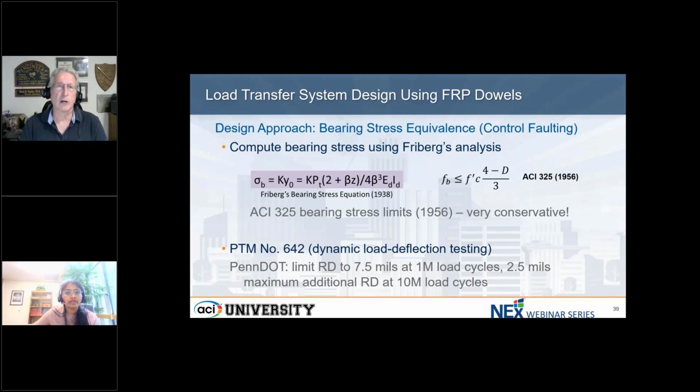You have guidance for using steel bars in those situations, and I guess a lot of times we increase the size of the diameter of the bars for steel when we go to dowel bar retrofit. Sometimes I would use proportionally the same size. If you're matching behaviors, you'd use proportionally larger bars for the FRP as well, I suppose. Although again, experience is indicating you probably use the same size bar.